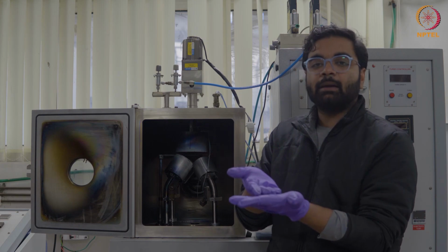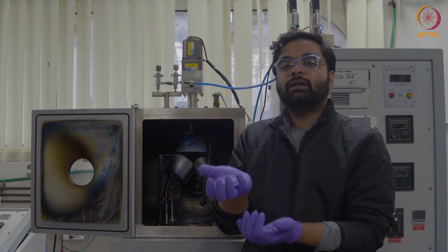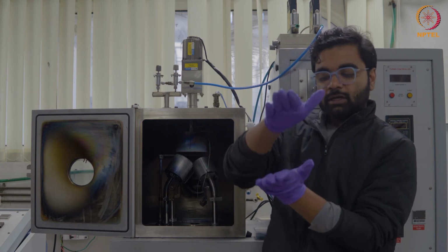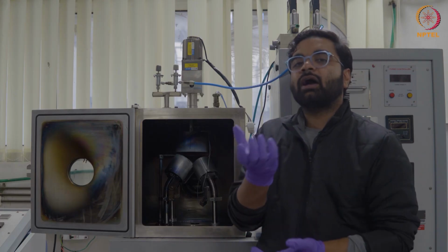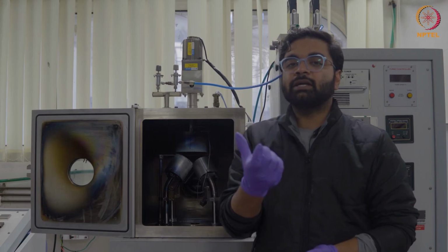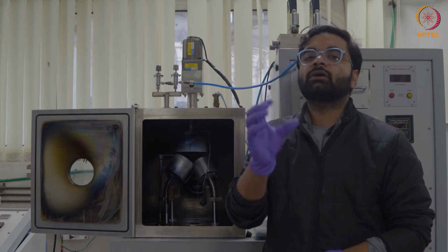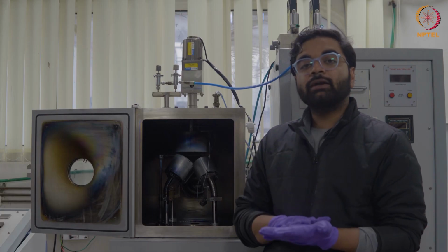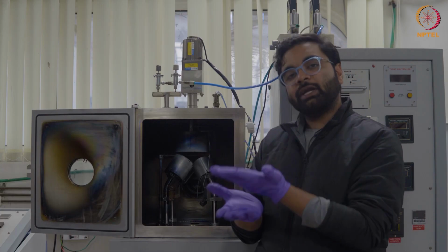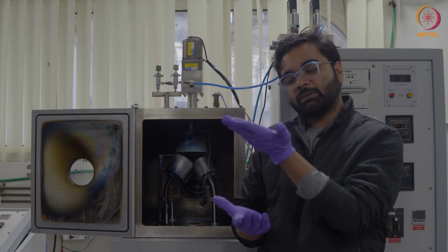The phenomenon that is happening over there is called local welding. Because the material, once it's transferred onto the substrate, has to weld on the surface, or join the surface, for it to have a good amount of flexibility. At the same time, the strength of the sensor that is being formed should also be intact. So to create that local welding on the surface, we do substrate heating. During transfer, the acceptor substrate is heated.